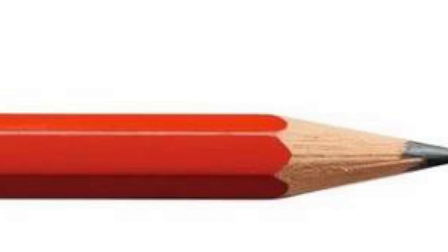Now, because precision and organization is needed, you can't just start drawing with a hard pencil. You want to draw with a soft pencil first, so that when you are sure of your diagram or you are cleaning much, you can easily clean and it will not create a stain, because you want neatness. And for those of you that are writing international exams like WAEC, you know that when you are drawing, neatness is always emphasized. They write it on the paper. So you need B pencils for your construction work. Then when you are done, you can now use your H pencils.